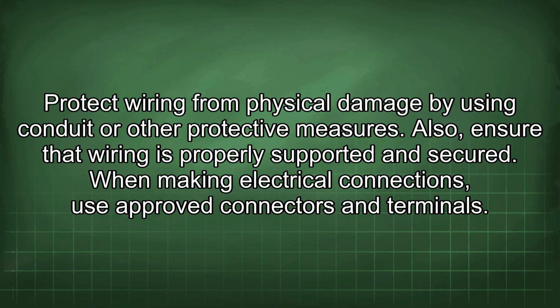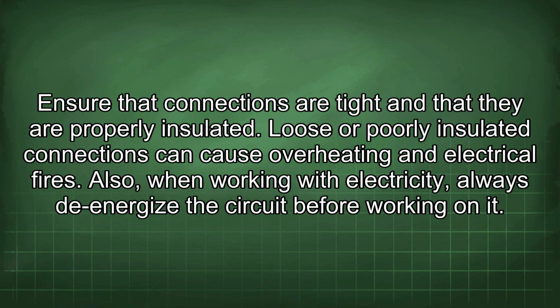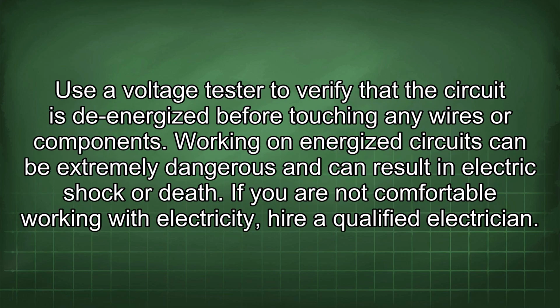When making electrical connections, use approved connectors and terminals. Ensure that connections are tight and that they are properly insulated. Loose or poorly insulated connections can cause overheating and electrical fires. Also, when working with electricity, always de-energize the circuit before working on it. Use a voltage tester to verify that the circuit is de-energized before touching any wires or components. Working on energized circuits can be extremely dangerous and can result in electric shock or death.